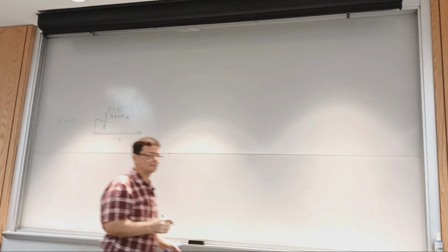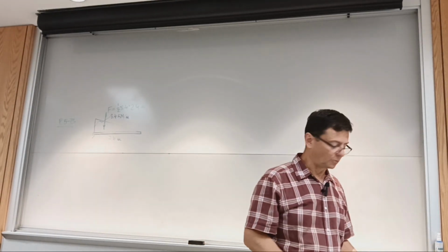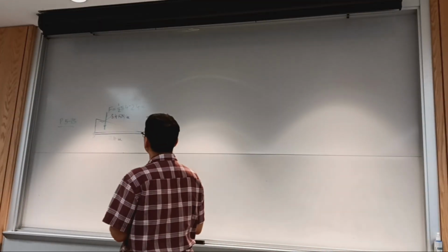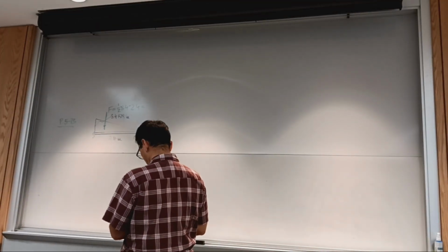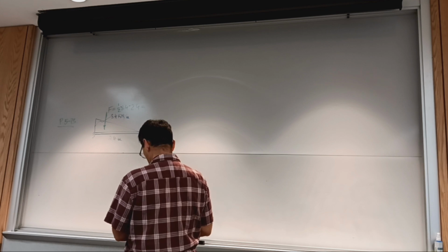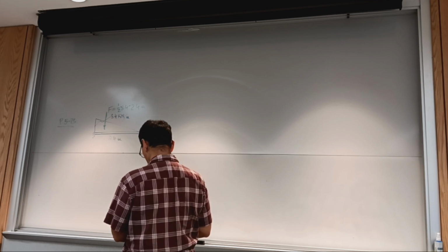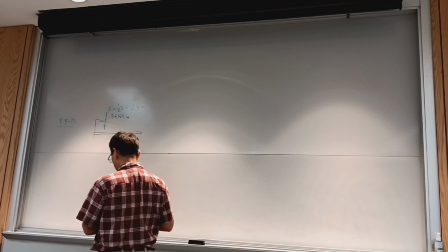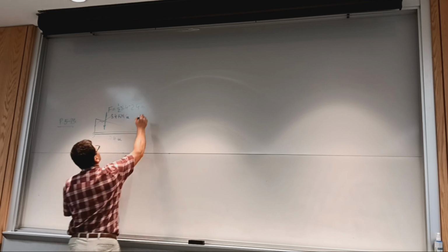That's the magnitude of the equivalent force when it comes to the response of the support, but not the response of the beam. So 8.4 times 2.4 over 2, and this is 84.672